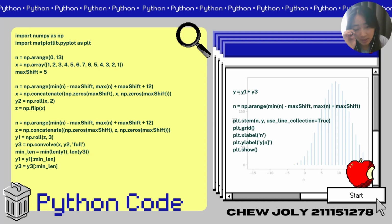Then repeat the step to adjust the range of n and z. Then y1 is the circular shift and flip of the z signal 3 positions to the right. Then the np.convolve function is the convolution function in Python. It performs a convolution between the original x signal and the circularly shifted y2 signal. Last, store the result in y3.